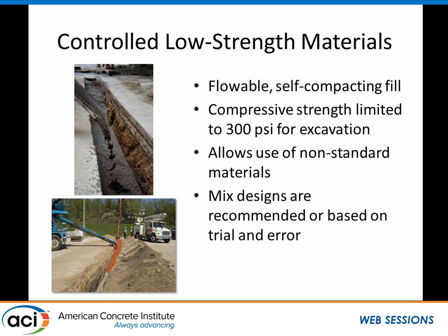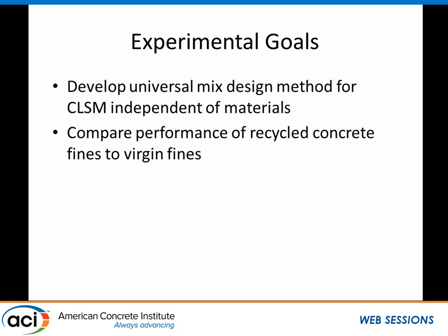So our goal here is to take this opportunity to use a recycled material, these fines, and create a mix design methodology that will allow us to get to a useful, targeted performance efficiently. Our experimental goals, therefore, are to develop a universal mix design method for CLSM, independent of materials. Of course, we're thinking about the recycled fines, but it could be any kind of fines. And compare the performance to what we would get using sand or virgin fines.